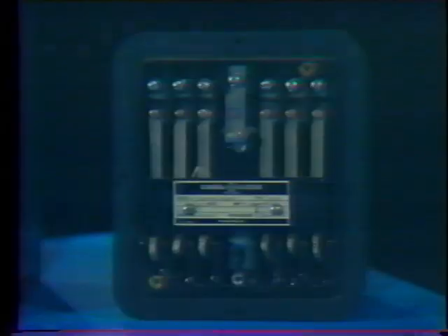The operation of a relay is a bit different from the operation of a solenoid. In a relay, the core is always in the middle of the coil. The purpose of the core is to strengthen the magnetic field that's produced when current flows through the coil. When a relay coil becomes magnetized, it typically pulls a metal plate to it or causes a metal plate to turn. A relay constructed like this one pulls a metal plate, called an armature, to the coil to operate a contact or a set of contacts. It's the most common type of relay construction. We can see how it works in this simplified graphic.